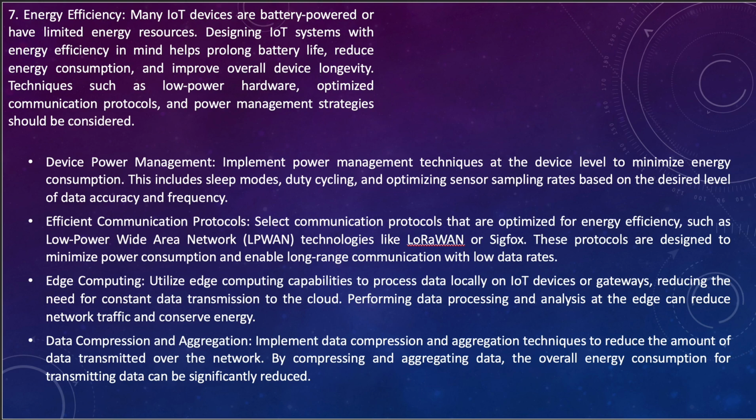Device power management. Implement power management techniques at device level to minimize energy consumption. This includes sleep mode, duty cycling, and optimizing sensor sampling rates based on the desired level of data accuracy and frequency. Now, when I'm going through these points, you should be able to recall the examples that I was giving before, why we need efficiency in IoT devices.